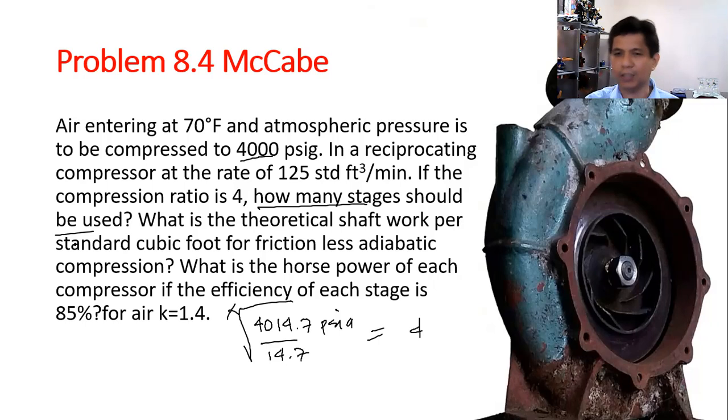So basically, this is the working equation. Basically, the working equation in order to find the number of compressors is P2 over P1. Okay, P2 over P1. Tapos, you just take the root or 1 over x is equal to 4. So itong 4 na to ay rule of thumb. Ganun lang yun, in order to find the number of compressors in series.